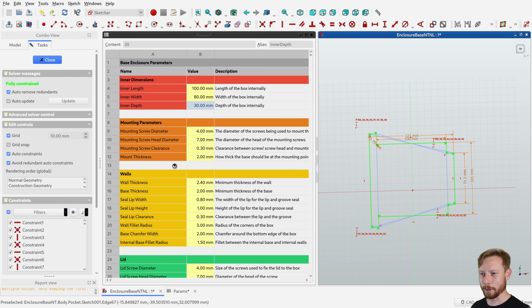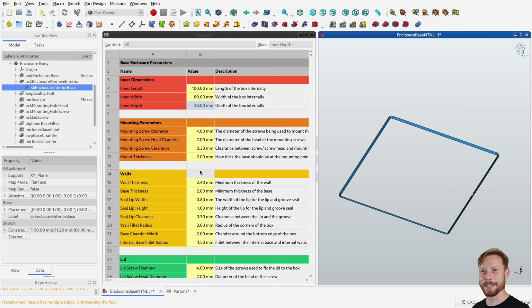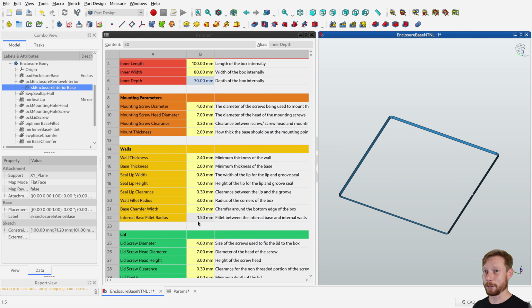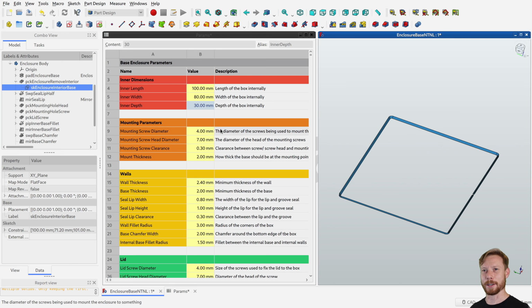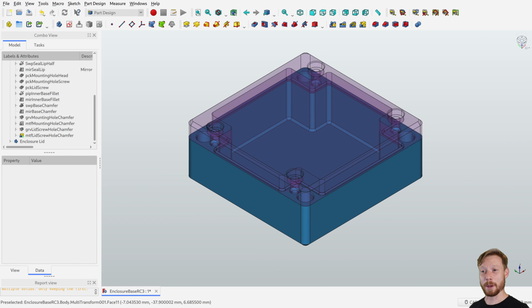So you can tell I put a lot of effort into this spreadsheet and released this box when it was broken. But that brings me to rule number 3, test as you go. Every time you make a sketch, change the parameters and make sure that the sketch doesn't explode on you. Every time you make major changes to the sketch, do the same thing.